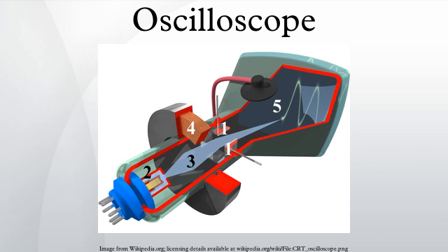Astigmatism can also be called shape, or spot shape. It adjusts the relative voltages on two of the CRT anodes such that a displayed spot changes from elliptical in one plane through a circular spot to an ellipse at 90 degrees to the first. This control may be absent from simpler oscilloscope designs or may even be an internal control. It is not necessary with flat panel displays.